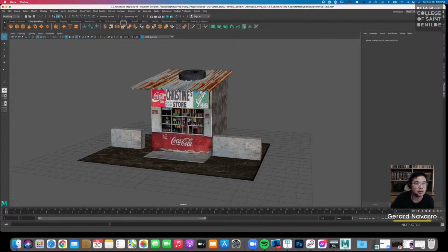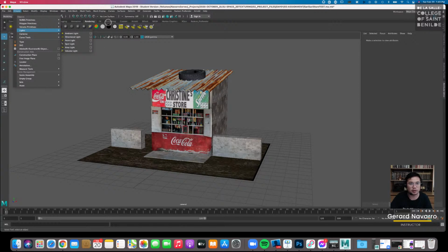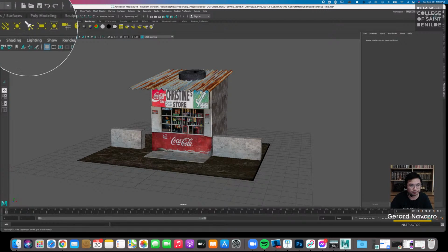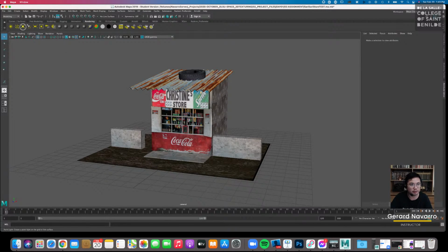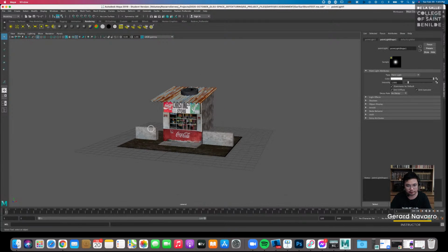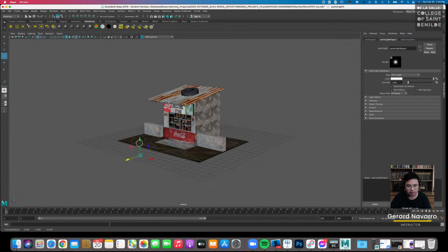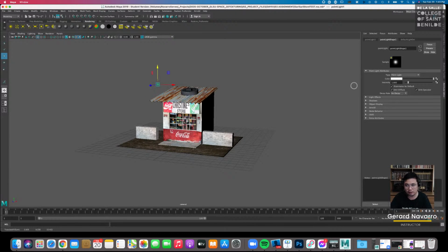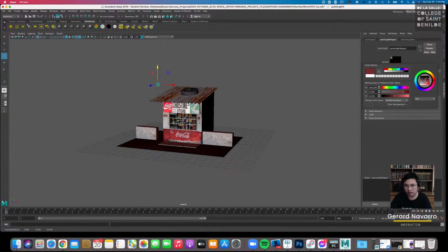Okay, so now you can actually add lights to your scene. If you want to play around with it, you can create lights. There's lighting here supposedly. Where is it in our tab? And rendering. So you can go to create lights or under your rendering shelf, you can just add a few lights like a point light, this one, and then press the number 7. What you can also do is add a background. So for example, let's complete the scene.